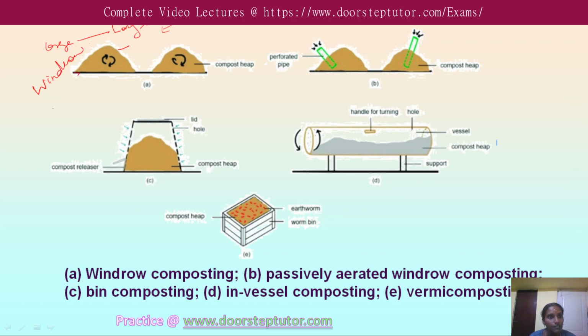Here, first, the mixture of MSW waste is shredded, and then it is alternately filled with soil material as well as the MSW, and it is also layered with cow dung for microbial growth. The cow dung we use is not a fresh one.